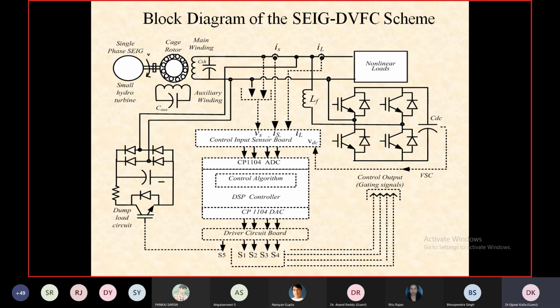But if the shape of the voltage waveform is sinusoidal and the shape of the current waveform of the load is a square wave or of some other shape, maybe triangular, maybe square wave, maybe spiky, then system is non-linear.